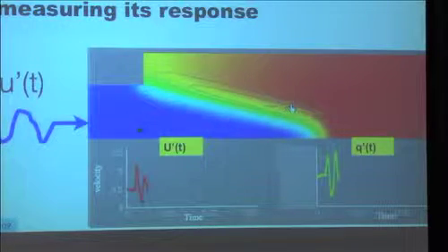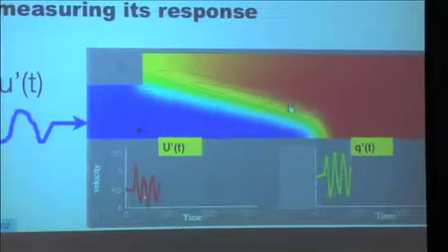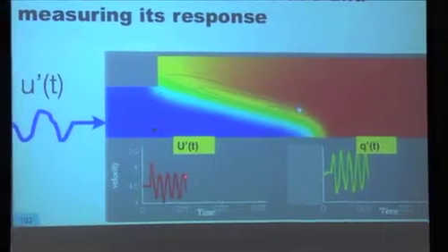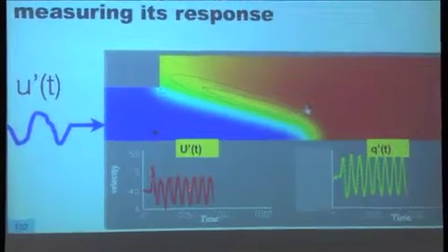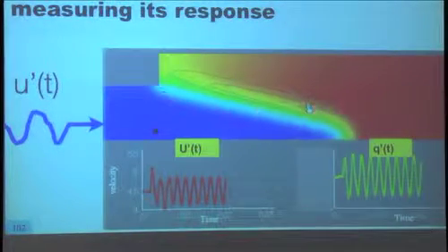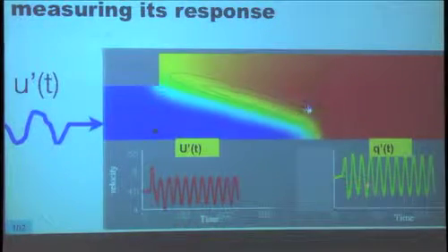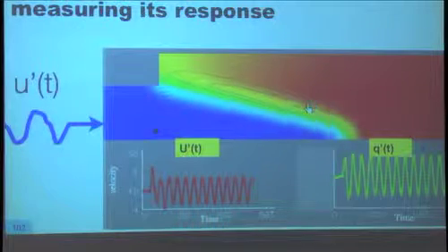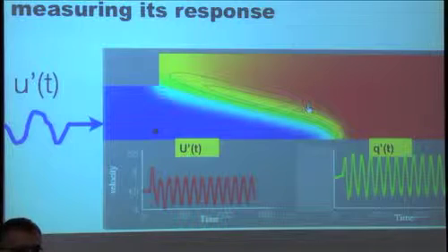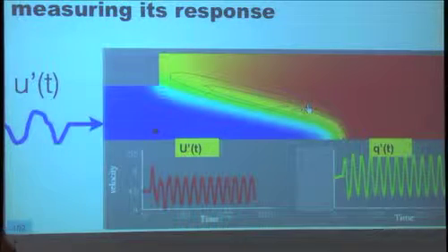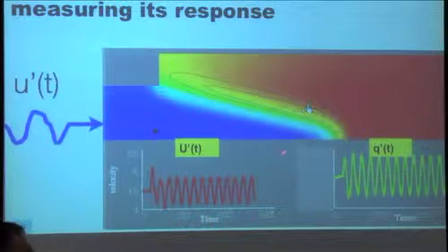a premix flame, laminar premix flame, and you can see here, after a few oscillations, we reach a harmonic regime where the speed at this point is displayed here, and the total heat release is displayed here. Those are two sine waves. You can measure the delay, and so you know what tau is. Okay, the question was asked, how do you get the delay? In that case, this is a good way to measure the delay in a simulation.